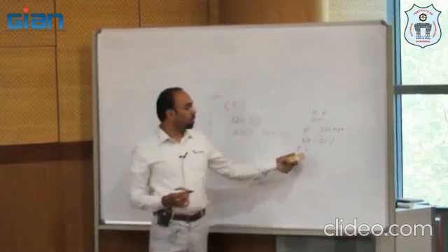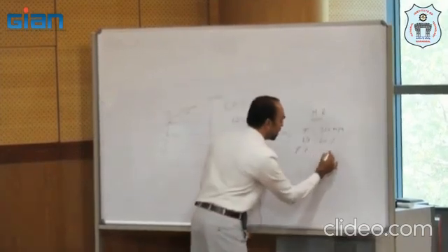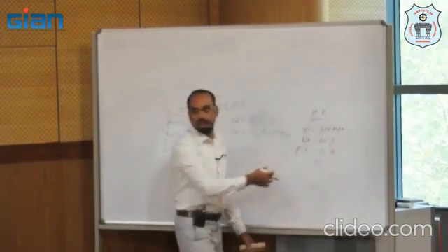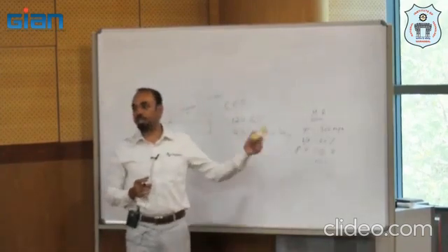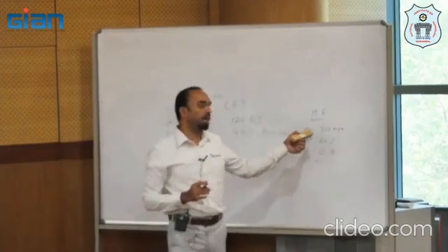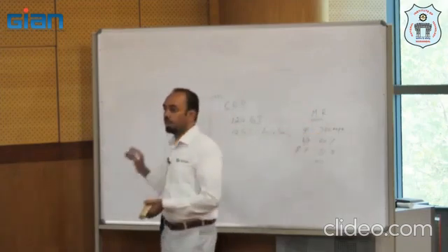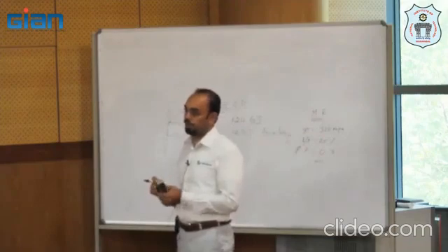So I have to choose for this condition, let's say 0.3. You can develop your own material which satisfies this condition. Any material I develop has to be 320 and above. If it is less than 320 MPa of yield, it will fail and is not suitable for this application.